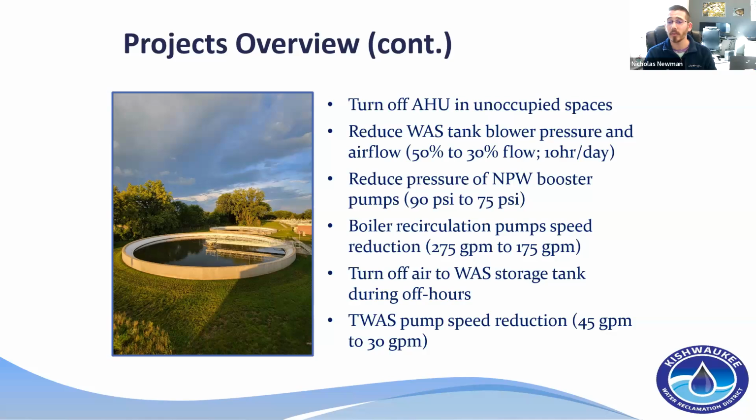Reducing our waste activated tank blower pressure and airflow. We reduced that from 50% of its maximum down to 30% of that flow. And previously we were running those continuously. So we were running that blower 24/7. And we were able to find that we reduced that down to only 10 hours a day to still get good waste activated sludge.